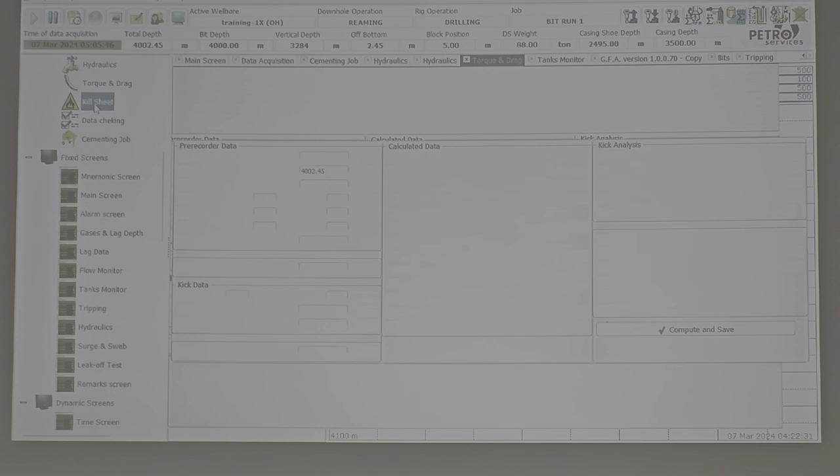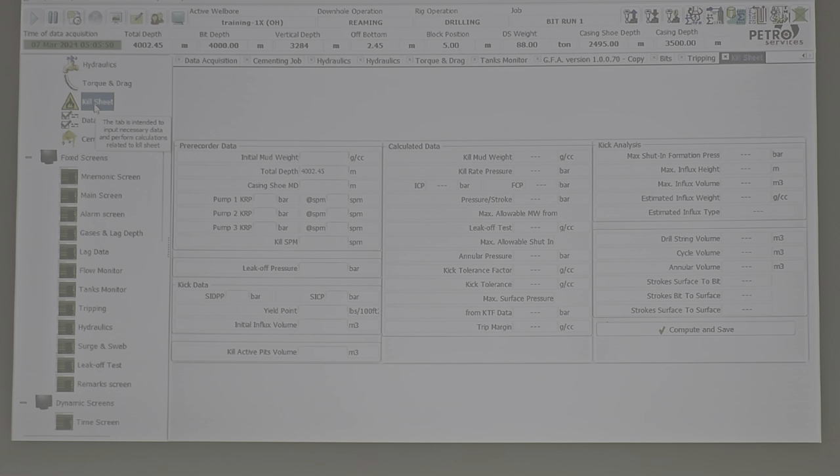Of course, this is a good function, the kill sheet, that you can identify in a well-control situation to the client what is the specification of the influx. If you have a gain, 5 barrel gain, actual gain, 10 cubic meter gain, and they are closing the BOP, they have shut in drill pipe pressure, shut in casing pressure, they have this measurement, so it means that the formation is producing gases, which is pushing mud out.